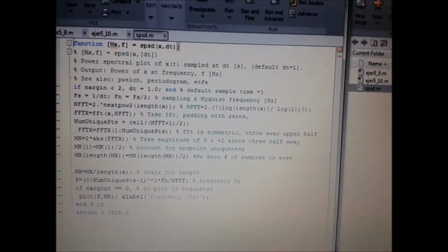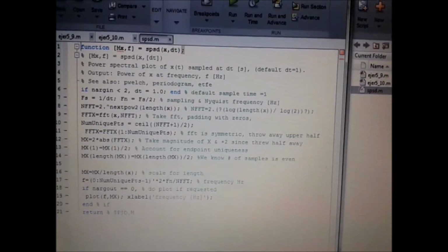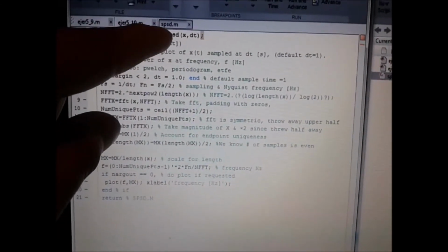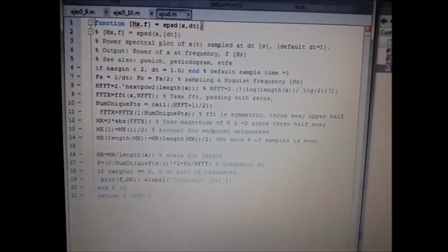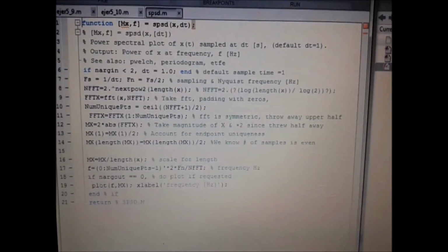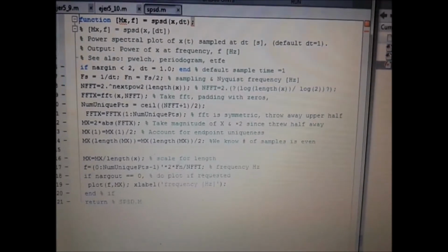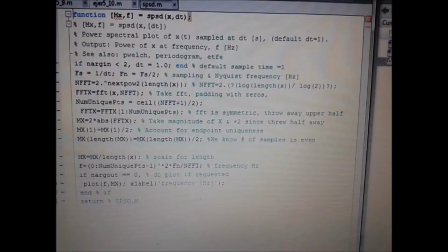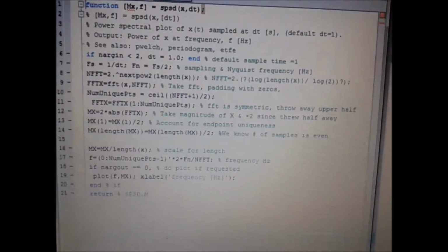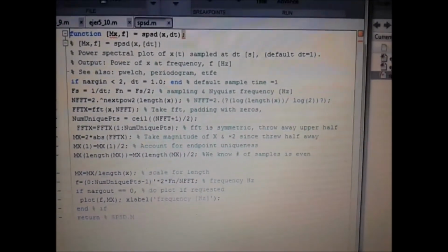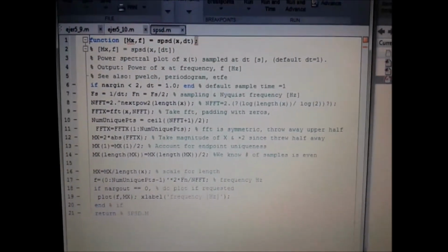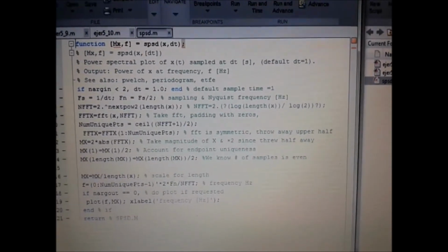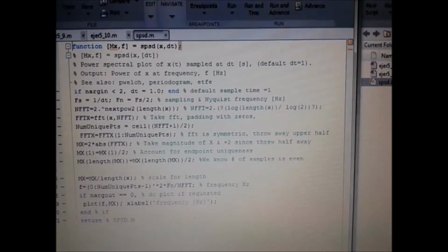I talk about exercise 5.9. The function created in this exercise is PSD. This function will use the Fourier transform to decompose the signal into different frequencies and display information. Since we have assumed that the input signal is real, we know that the Fourier transform will be conjugate symmetrical about the Nyquist frequency.